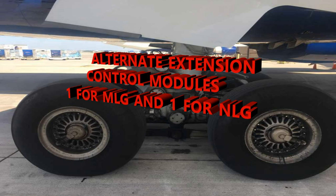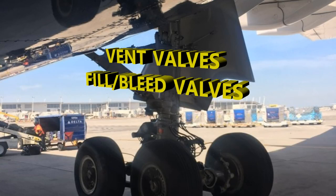All right, and just to remember, I mentioned the alternate extension control modules; there are 2. There's going to be one for the main landing gear and one for the nose landing gear, and they are labeled A and B. Okay, so there are 2 of those. Now you know about the power packs. There's one for the nose landing gear and one for your main landing gear, and it's isolating the hydraulic circuit right from the normal hydraulic supply. And then you have vent valves, and you also have fill bleed valves that are installed on the vent valves.